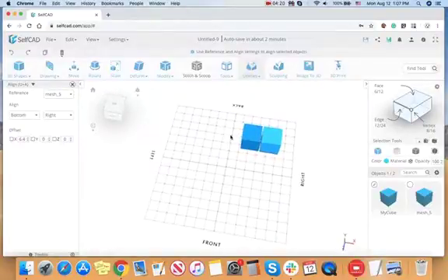If you want to align it in the other direction, going from the center of the scene to this side, you will need to do the same thing, but you'll have to do minus 6.4, because this way goes negative on the x-axis. And that will do it. Otherwise, 6.4 will actually get it inside the object. So that's how we do this.